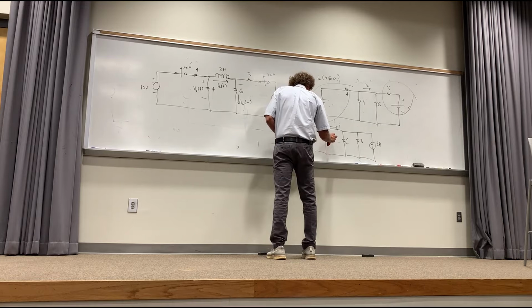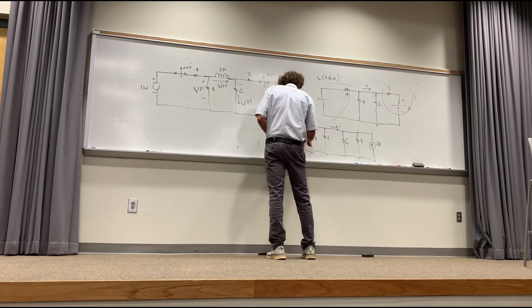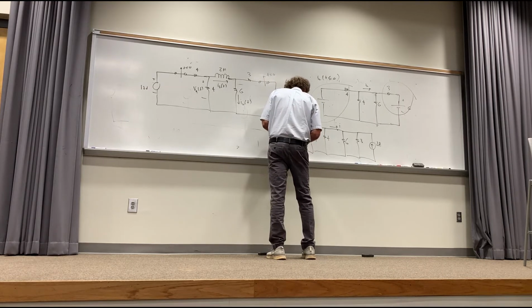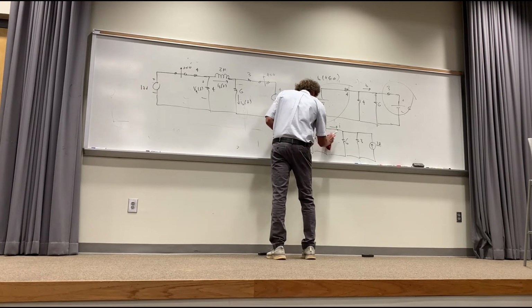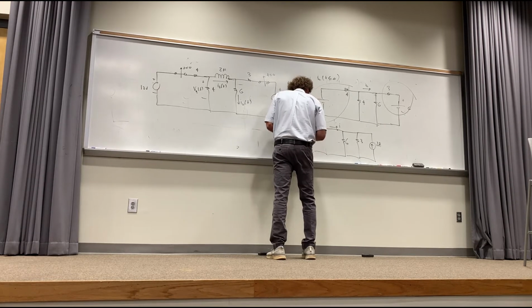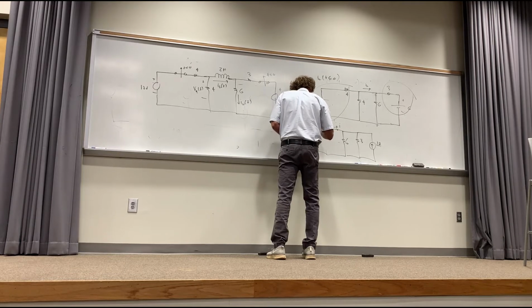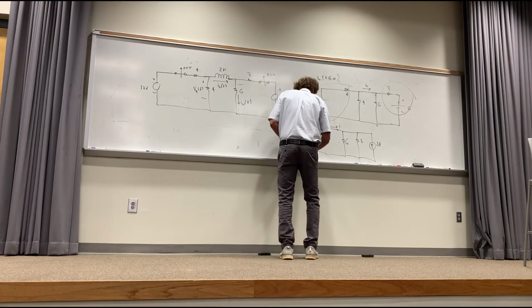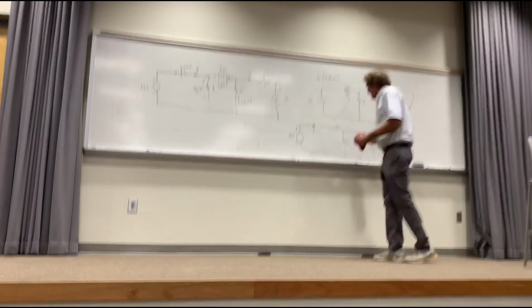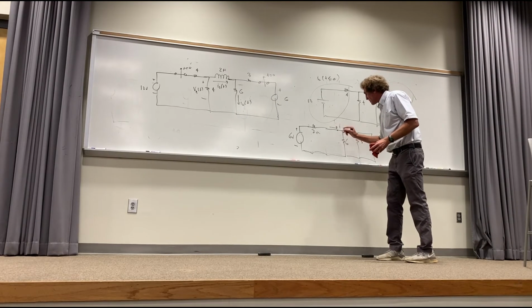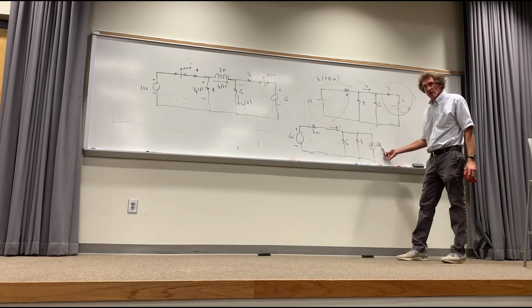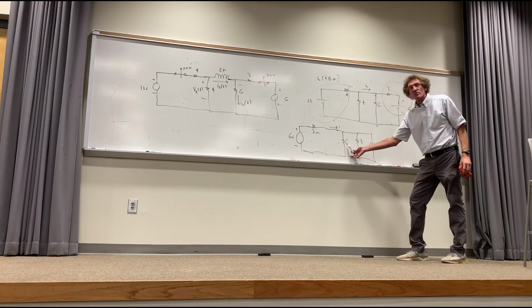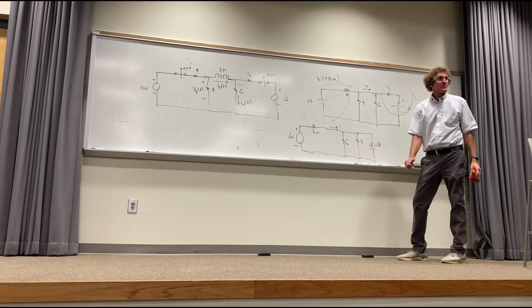So this is gonna be 2 times 3 is 6 volts, in series with 2 ohms. Now remember, this is where we want the current, right here. Now that's 2 ohms. What am I going to do here? 3 in parallel with 6 is, yes?